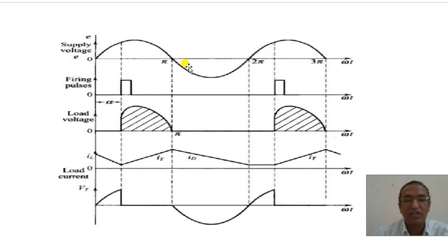What happens during the negative half cycle of the input? The thyristor becomes open circuit, so no current flows through our circuit. There is no current through our thyristor, and no voltage is supplied across this thyristor. At the same time, at the time t here, whatever the energy stored by the inductance when the thyristor is forward biased, that energy is stored in this inductance. The inductance will start to discharge.